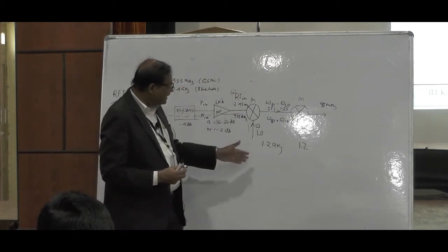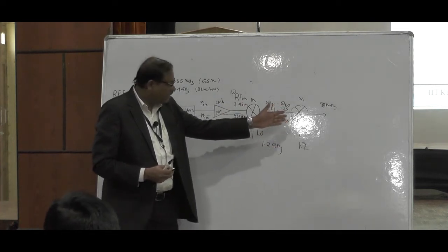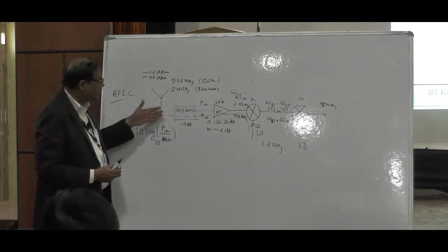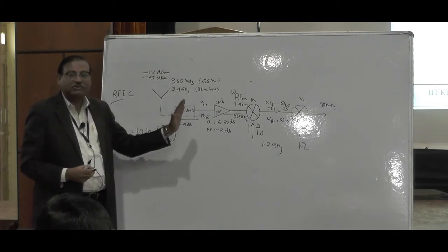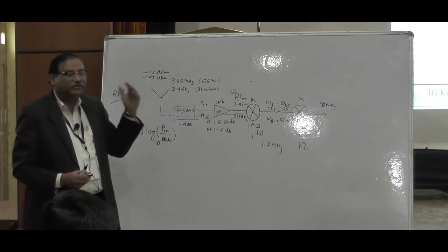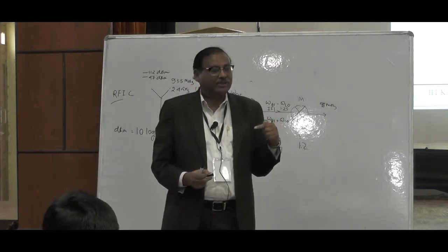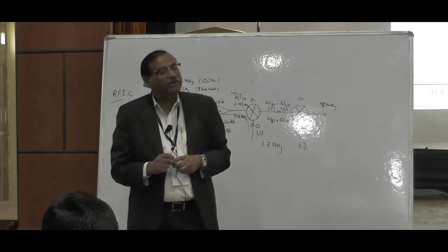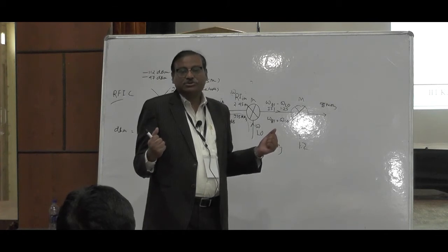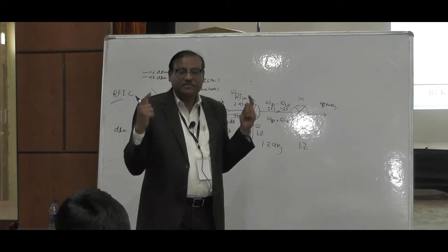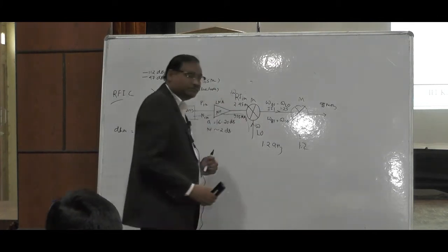Okay. Now if there is a leakage, say 1.25 gigahertz from the mixer, it goes through the low noise amplifier and the filters to the antenna. But again it reflects back. But what is the frequency? Our RF frequency is 2.405 gigahertz, but my local oscillator is 1.25 gigahertz, so I won't get any problem. So you can actually differentiate your local oscillator from the input RF signals. Clear? So that is the genesis of this superheterodyne kind of receiver.